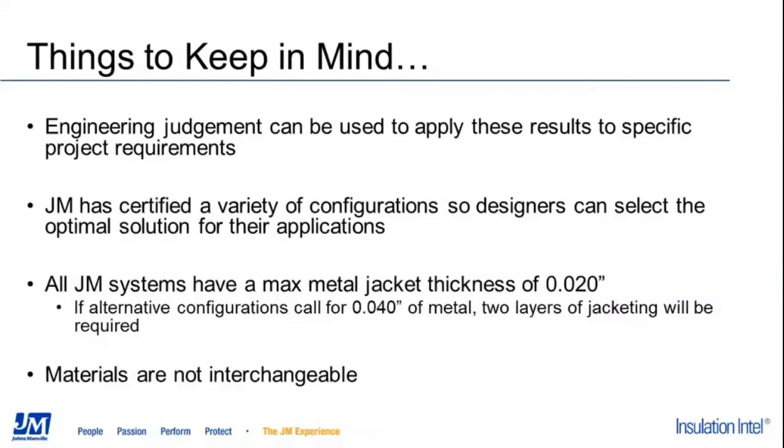And then a couple things to keep in mind is that you can utilize the information that we've reviewed here today and apply engineering judgment to look at the insertion loss results that are achieved in each of the 4 classifications that we have, and determine how they can be applied for other requirements you may have. We have, as I said, tried to certify everything to the most complicated requirements, so that then the designers can take a look at what might be the optimal solution for the particular project that you're designing that acoustic system for.